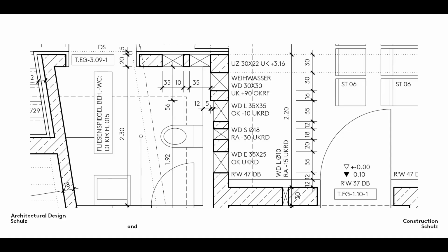Any text that needs to appear in construction drawings should be placed in text blocks so that different texts are clearly separated. Once again, to avoid confusion, the information should be placed as close as possible to the component to which it refers. Where this is not possible, a text block should be linked to the relevant component by means of a leader line.